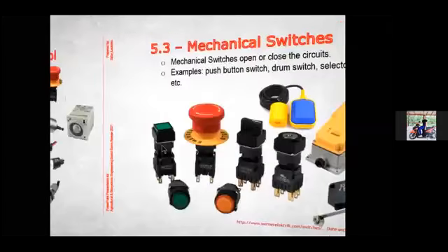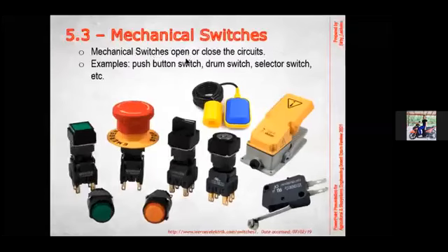Okay, so for the first one, we have the mechanical switches. Mechanical switches open or close the circuits, and there are a lot of them. For example, we have the push button switch, the drum switch, or the selector switch. This one is a selector switch, wherein if you rotate this knob, you can switch some circuits on or off. And we also have push button switches, and some switches also include indicator lights.